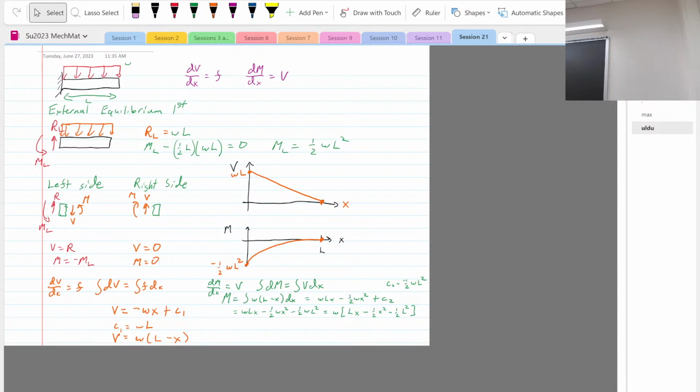You get it? Oh, yeah, yeah. Since it's on the neutral axis, y is equal to 0, so that's the maximum value, and then the bending stress is 0.